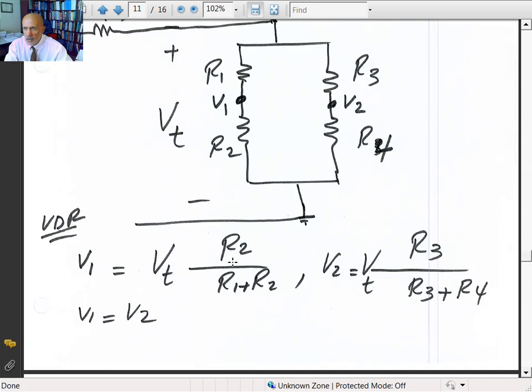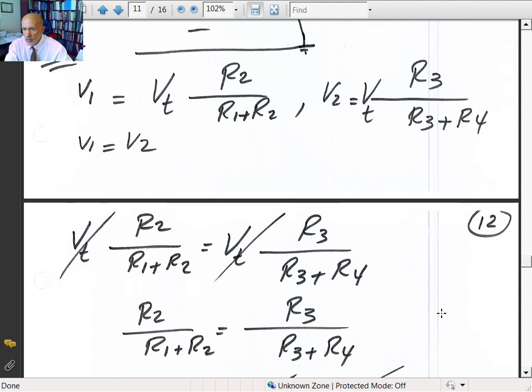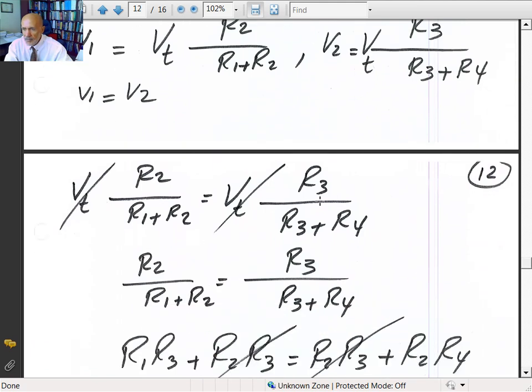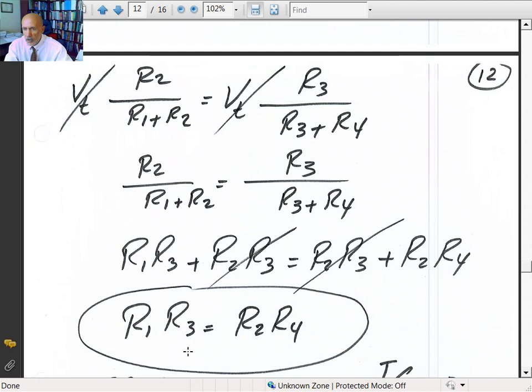Sorry about that, that's a typo. It should be, using the voltage divider rule, V2 would be equal to R4 divided by R3 plus R4. So you multiply it out. Let's see, you got R4 times R1. So R3, that should be R1. Sorry about that, you can make that correction.